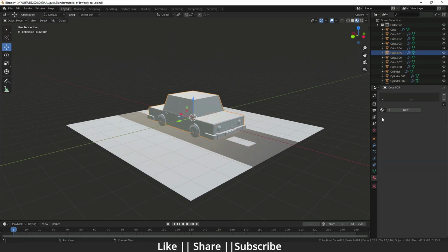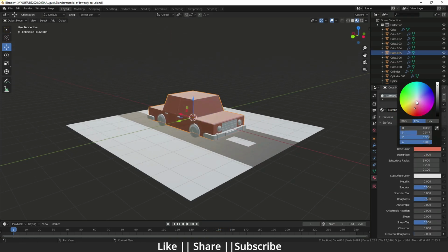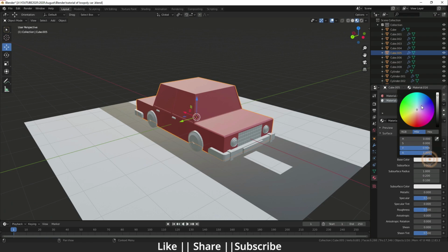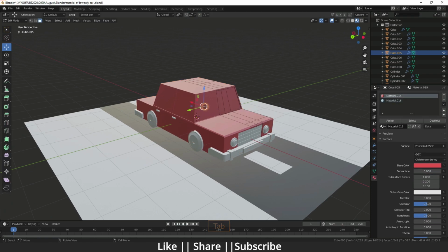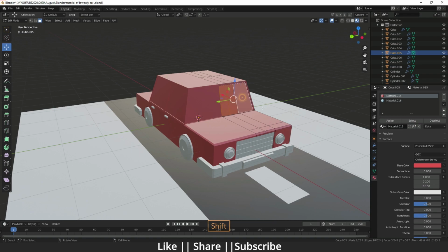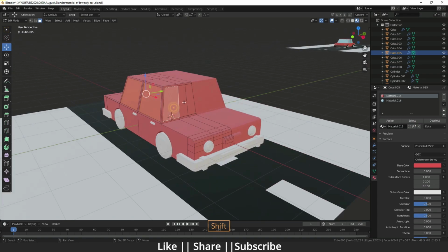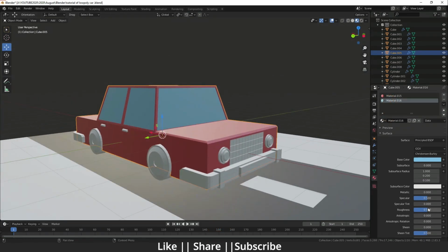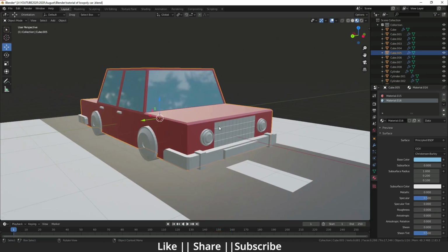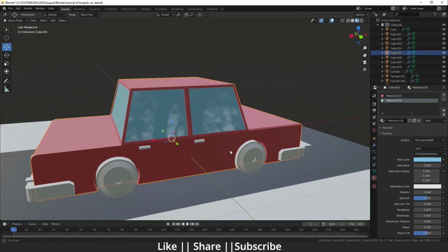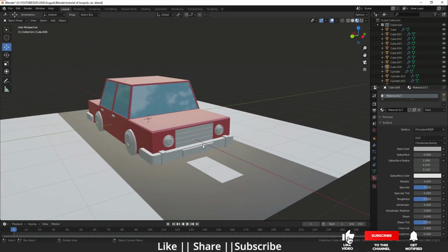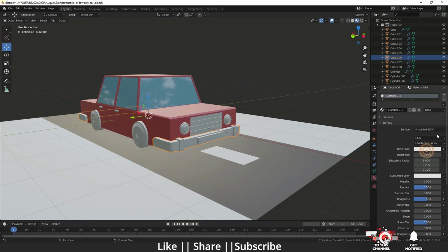Now I'm going to texture our car, adding some color here, so that color is perfect. Now I'm going to add another color for the glasses, so I'm going to select the glasses. Here you can see we are selecting the glass and adding the material. Material is ready. I'm going to decrease the roughness, so we have that kind of shine in our glass, and I'm adding some gray color here, and after that the same black color here.